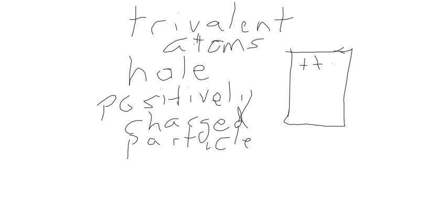So that's like I've got some material. Again, it's my silicon crystal lattice to start with, doped with these impurity atoms that had only 3 electrons, and that gives us what we call p-type semiconductor.